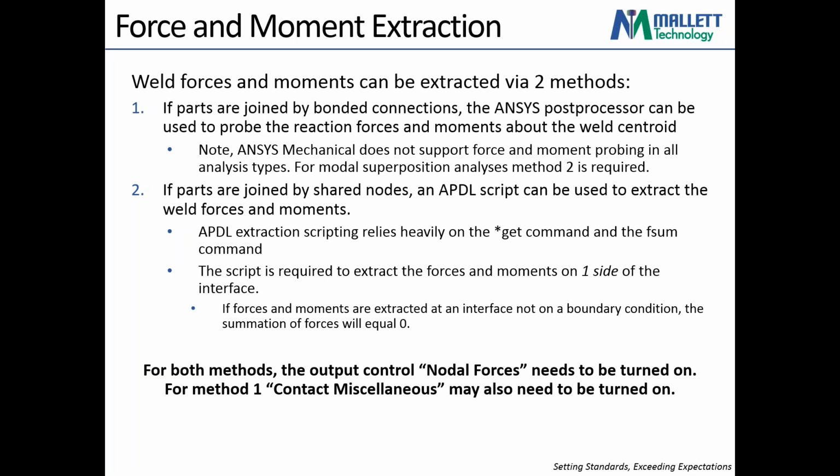So for those types of analyses, we almost have to go to the second option, which is the shared node option. And you can actually use the APDL script extraction method for non-shared nodes for bonded contacts, but at that point you might as well just do shared nodes. So the script that we have here at Mallett does rely heavily on the *get command as well as the fsum command.